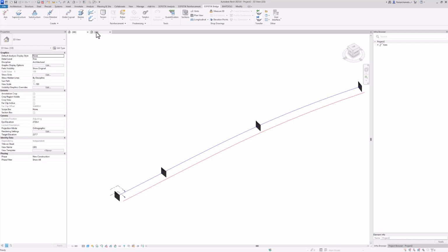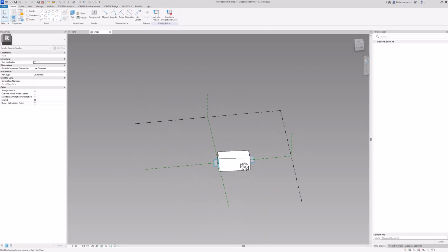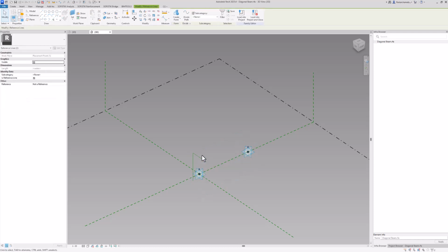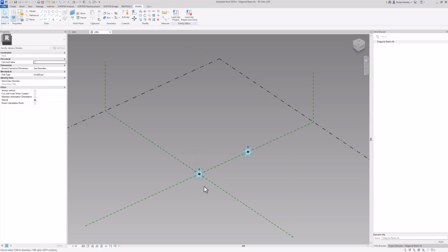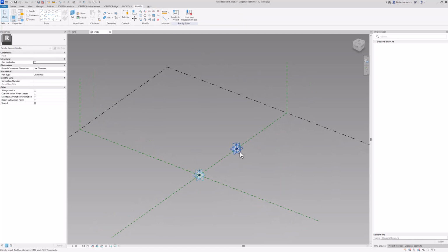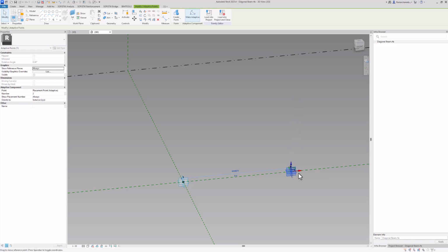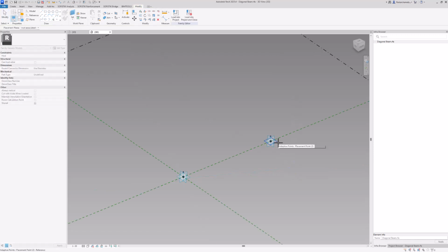So I move back over to the family where I created our rectangle, and I get rid of all the references I created. Because you remember, we actually not only want to have a longitudinal beam along our axis, we also want it to be diagonal, meaning with additional height information. To do so, we have to think about what's necessary to properly create this, meaning we first up need an additional point for the height. So at the end of our beam, I want to create a height variation.